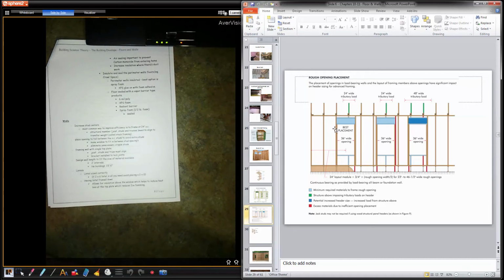Some people even go to the extent of making sure that the windows are exactly fit in between stud components. Instead of going with 36 inches here, maybe go with 4 feet. So the window's a little bit bigger. But at least you're then eliminating this section of stud. That'll be gone. But there's a point load there. So here we didn't require a point load because it's sitting on top of the floor joist. Unless that's a TGI, then you'd have to block either side of it because it's not strong enough to carry the weight. But if that window was bigger and hit this one, that would pick up the weight.